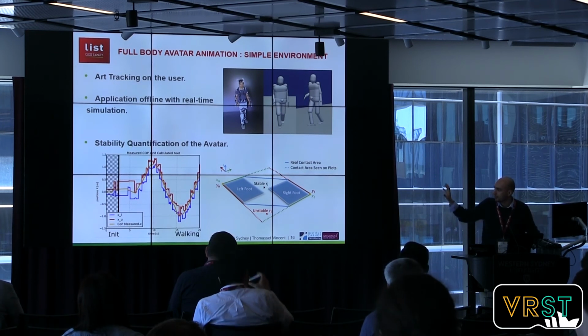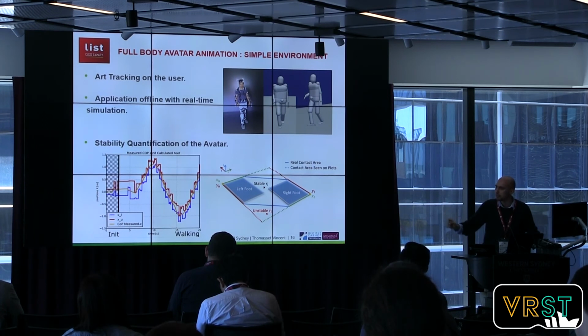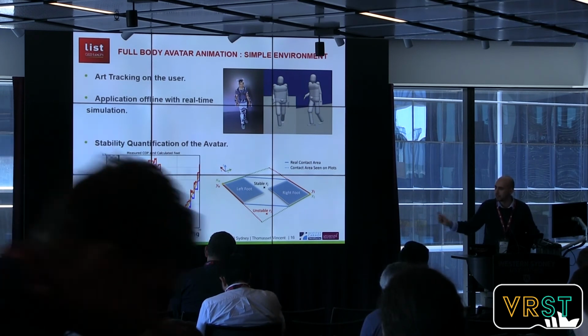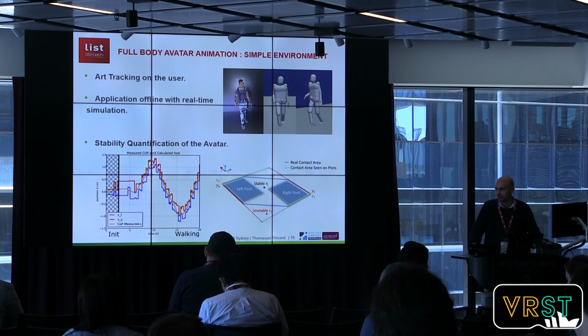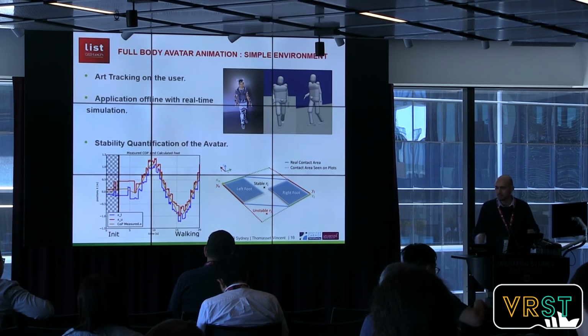So with alpha, which is now a variable, I have a variable time step. Depending on the stability and the velocity of the user, I will have different time periods and different step lengths, so it feels more human-like for the user. It's quite complicated because in robotics, all the algorithms have one constant periodic time for the step, and it's quite complicated to find an algorithm with variable step for robots, because robots don't care if it stays the same.